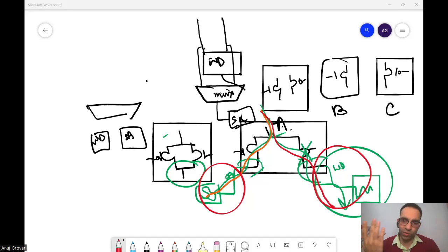See, anyways, there was a wire going towards the write driver, there was a wire going towards the sense amplifier. Earlier that wire was a single wire, now there are two wires. Okay, there could be some additional metal routing required, but only locally in that mux region. Otherwise, there were anyway two independent wires. Yes, sir. So you do not yet have that kind of layout experience. That's why these questions are coming. But you will see that overall you will save on capacitance without any penalty on area actually.